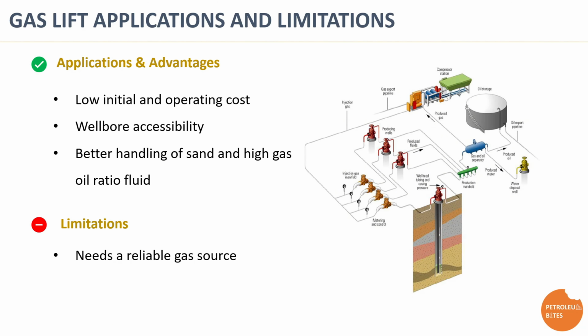Gas lift requires a reliable and continuous supply of gas injection at stable rates and pressure to sustain production. Meeting these requirements often demands significant upfront investment in infrastructure and surface facilities to ensure a continuous production cycle.